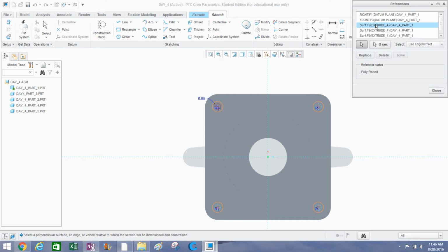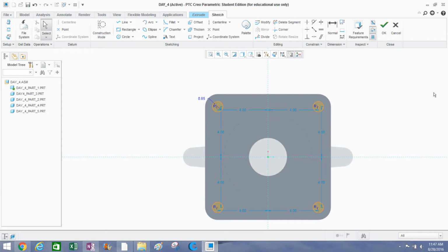So click on the first reference, press the delete button, and we're going to click it 4 times. And by the delete button, I mean the actual one that says delete, not backspace. Click delete, and you'll see now we've come back to our 2 planes. And now if I hit close, you'll notice it puts all of my dimensions back in there.